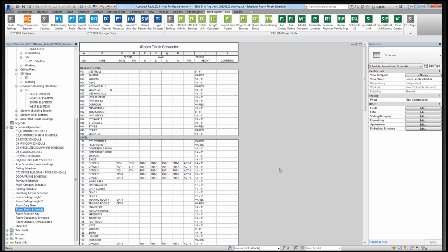And so another individual said that in their Revit model, the volume of the room is not controlled by the ceiling object. So the ceiling itself has the room boundary on, but the limit offset basically is what's calculating the height of the room. And that's fine. If you've got a top limit offset on that room, and you're carefully controlling that, you can use that directly in Revit. You don't even need to run extra math if you're actually leveraging it.